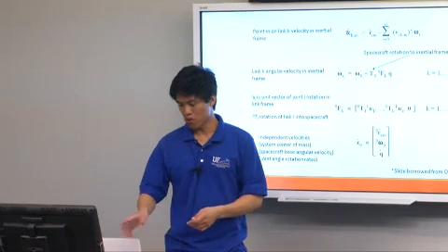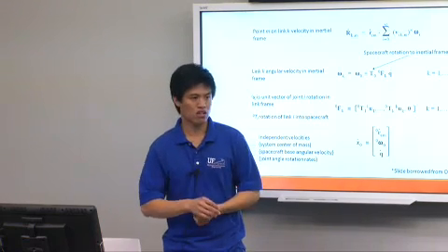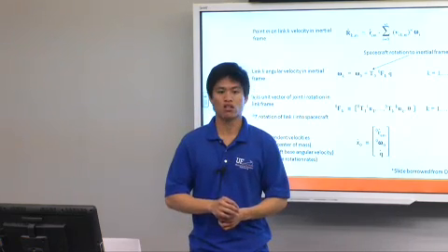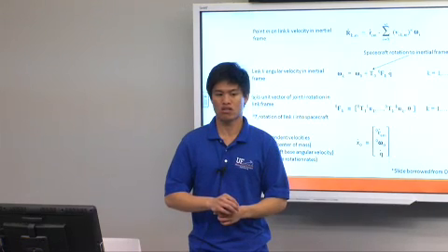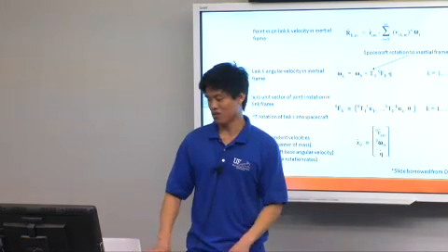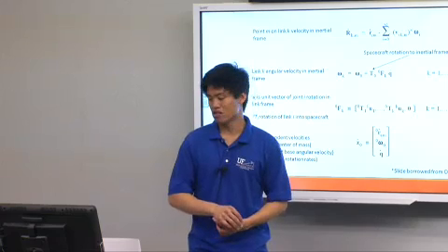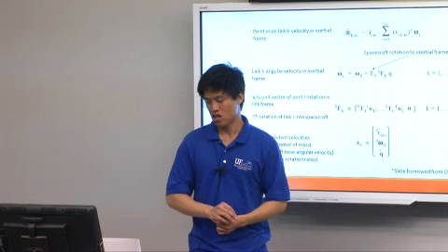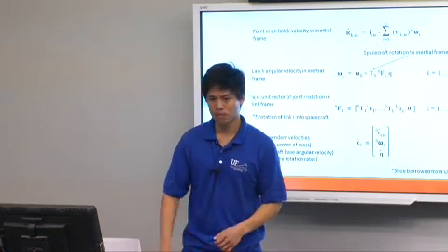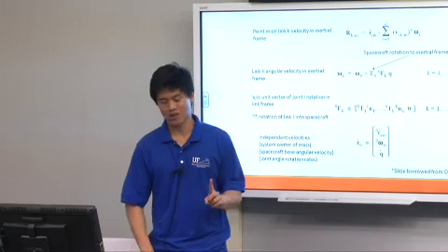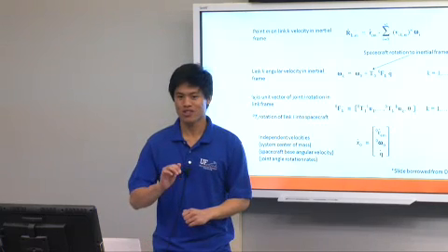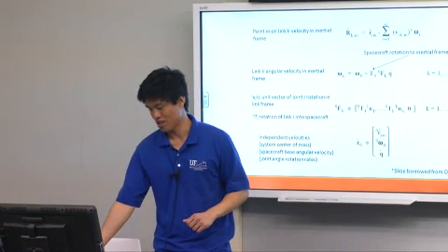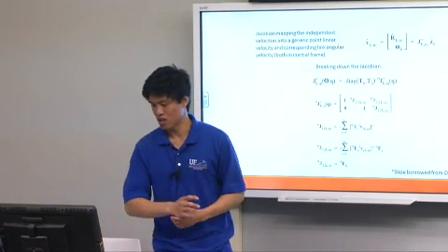So the important point here is that when we do Lagrange's equations, we need to choose generalized coordinates. They need to be linearly independent. And so what we choose, there's a little bit of technicality I'll go into later, but what we choose to represent the system is using the system center of mass, the spacecraft base angular velocity, and the joint angle rotations. So here I am assuming the joint angle rotations are only of a revolute joint, so they just are a planar rotation. And I'll explain why that's important in the next couple slides.